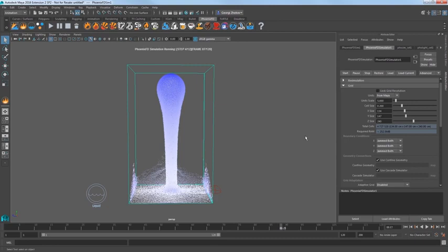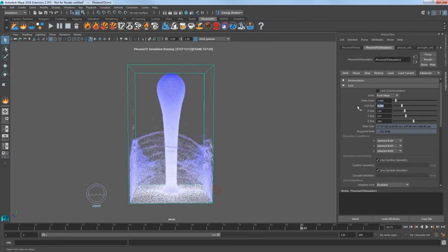It is, however, running quite slowly, so we can adjust the resolution to address that by increasing the cell size. Now, first take note that we have about 4.7 million cells to calculate in the sim, and this is our simulation's resolution. Setting the cell size sets the size of each cell inside that container, and consequently, how many cells are inside the simulator, thereby adjusting the resolution.